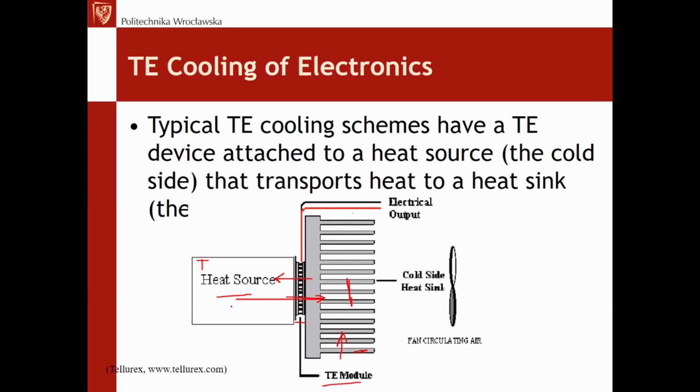So for example, if we want just to dissipate the heat because our power amplifier or the DC-DC converter is heating up too much, or some linear regulator is heating up too much, then it's enough to apply a heatsink and force the airflow if necessary.